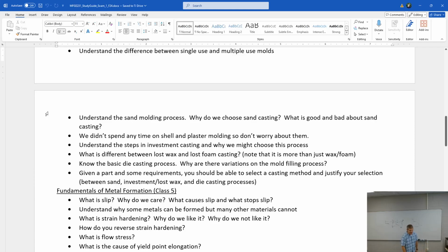There are so many ways. You can heat the mold. You can superheat the metal. You can make the walls of the mold smoother. You can use a different material that you pour, if that's allowed in the question, which it never has been so far in the questions that I've asked, but people continue to answer that anyway.